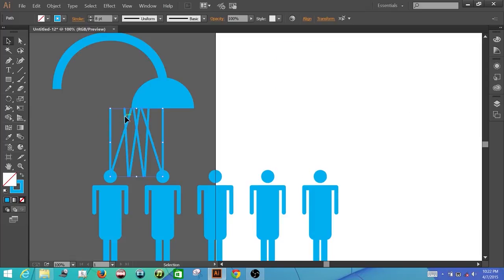With these copies, we're going to basically do the other side of the water. Click, hold Shift key, and move to the other side until you place them right there at the same location. You're basically matching the middle line of water, and that is how you place them at the same location. Release mouse, then Shift key, go ahead and deselect. And finally, let's come over here to this middle line, click once, and then press delete on the keyboard, because when we made the reflect command, we now have 2 lines in the middle, so we got rid of one.